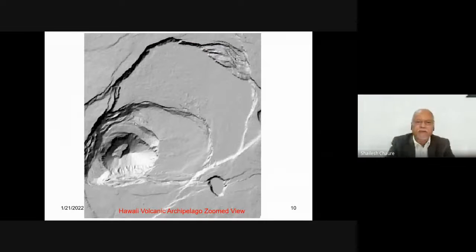Here also you can see the same area, but some part has been collected at a much higher resolution. So you can see the cracks in the rocks and all that, and even the depressions, everything you can see very beautifully. So if you want the elevation of some particular part, or you want a cross section of it, or a profile along any direction, you can always compute from this. Okay, because each pixel has the information of elevation.